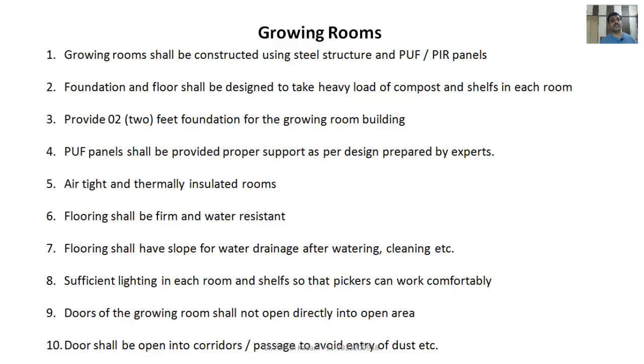So the growing room shall be constructed using a steel structure with PUF PIR panel. Now again, an important aspect I would like to highlight here is that people are not designing this steel structure, or this growing room area, or even the rest of the infrastructure, considering the earthquake and the wind loads. These are incidences that happen once in the life of the project.